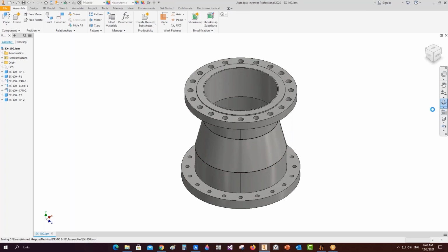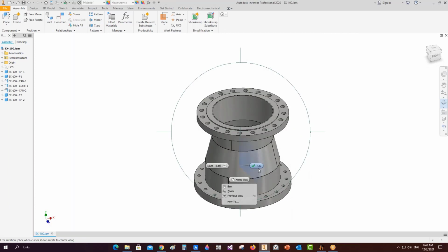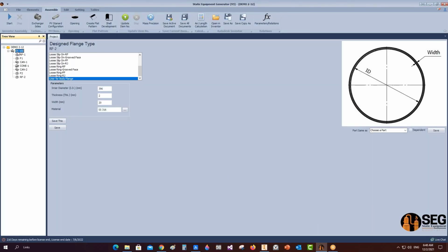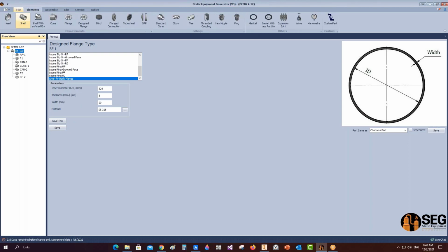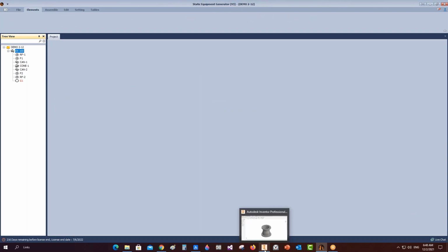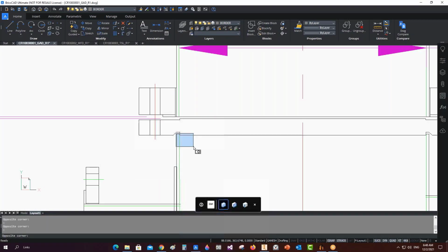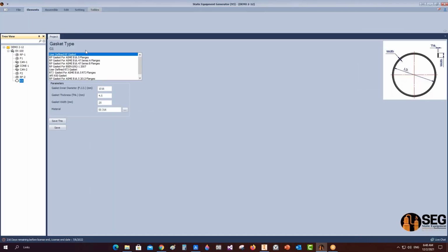Now we have this channel, the first channel here on those components, and now let's start creating the tube side. From here, we will select a gasket. So let's add the G1, which is the gasket between the tube sheet and this body flange. Okay, so let's add this gasket, and from here, let's select the user-defined gasket, and we will define the inside diameter, define the thickness, and width.